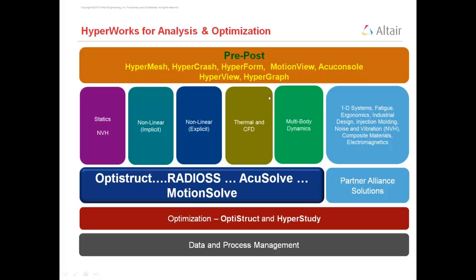The intention of showing these solvers is that for any CAE engineer, the progression is first model building, which is anyway the first step. Then you may start doing static analysis, thereby understanding the linear part. Then you may add a little nonlinearity, some nonlinear implicit work. And then the cream area comes, which is nonlinear explicit, with large strain, large deformation problems.